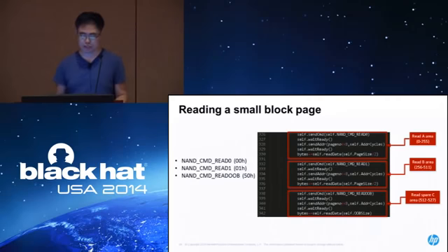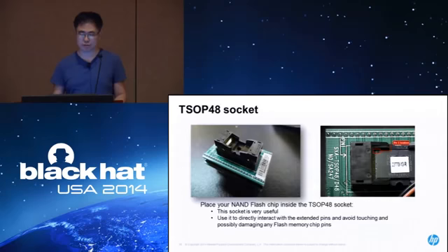So that is one good advantage of using this FTDI chip, because there are some other attempts using Arduino to read NAND flash memories. I guess it will be more of a hassle because they don't support these basic functionalities from FTDI chipsets. So the other equipment we need is the TSOP48 socket, and you can just mount the socket here, and this one is really convenient instead of soldering the flash memory to a breakout board.